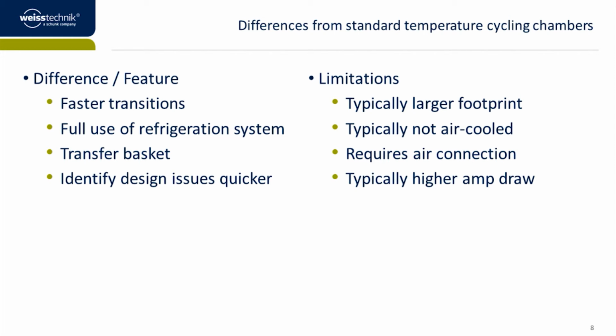However, on a thermal shock chamber, the refrigeration system and the heating system are on at the same time. So again, this isn't normally a large concern on most customer sites, but if you're not prepared for the amp draw, that is something that will need to be discussed before purchasing a test chamber.